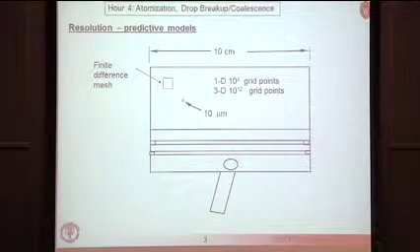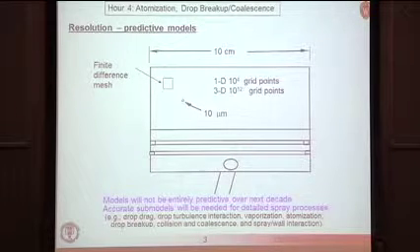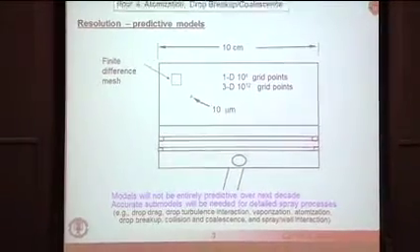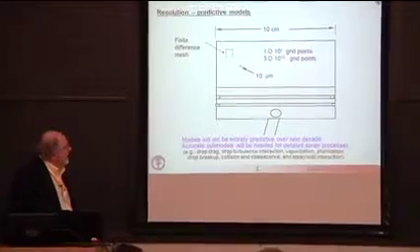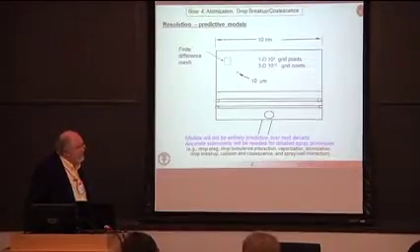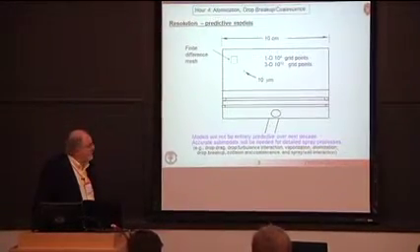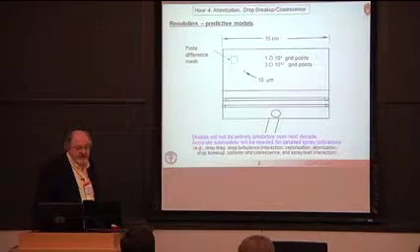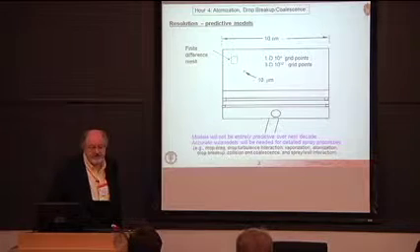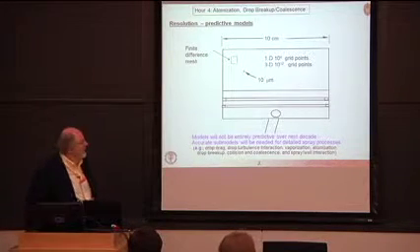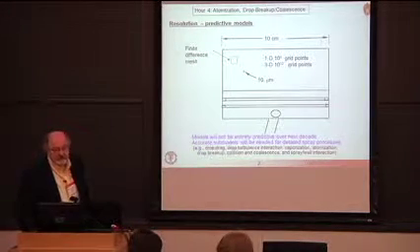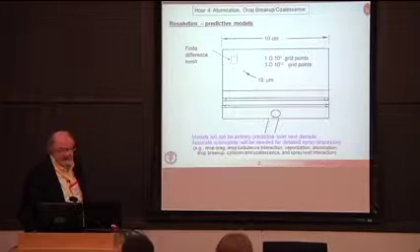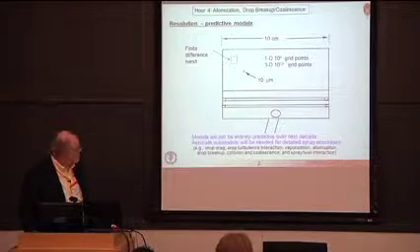So that means basically that we're going to be requiring submodels to describe processes that occur on scales below the scale of resolution of your mesh. Typical mesh numbers that people are using in simulations these days, really the maximum you see is around 1 million cells. So we're definitely far away from what's required for resolution down to the level of droplets in a spray.